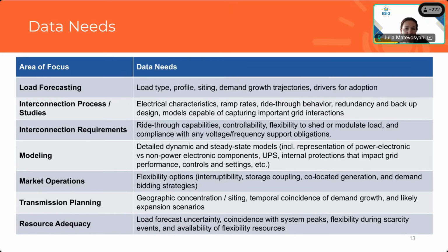For interconnection requirements, again, you need to understand ride-through capabilities, how controllable these loads are, how flexible they are to modulate, and whether they are compliant with any kind of voltage and frequency support obligations that may apply in the area. For modeling, it's kind of self-explanatory: detailed dynamic and steady-state models are required, and the models should include all of the important details for the study area focus.